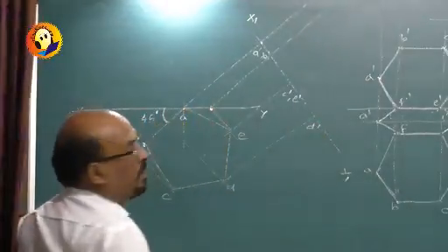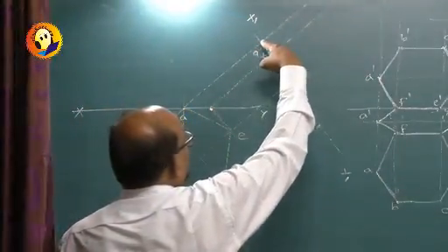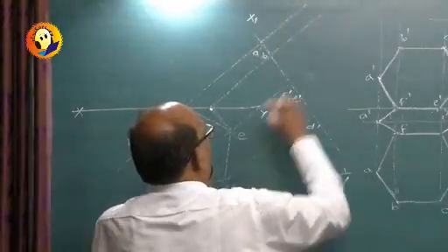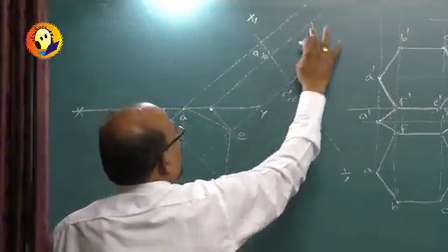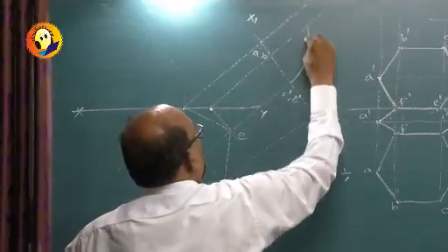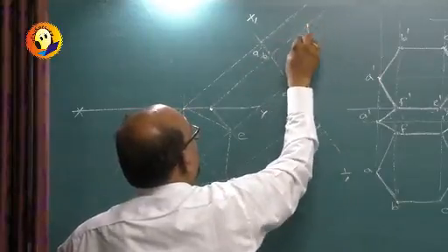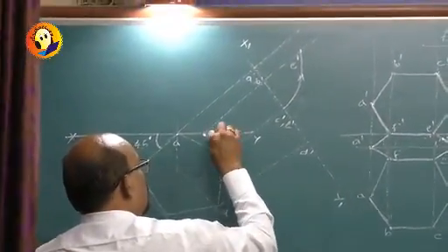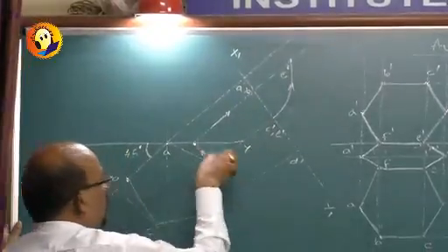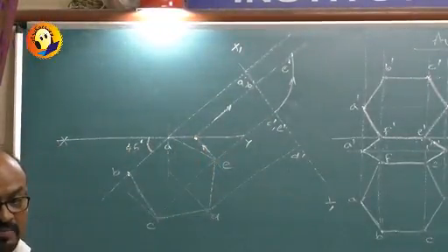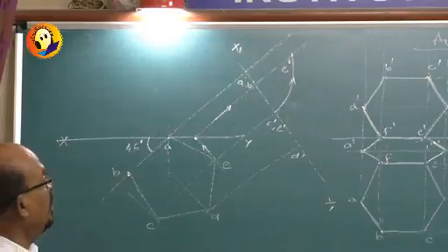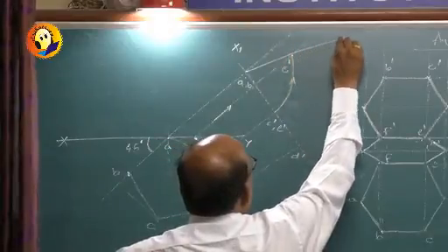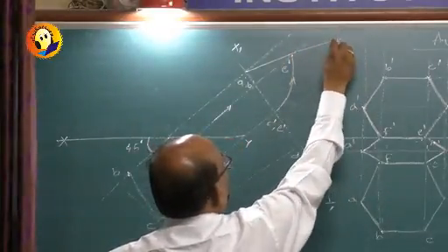So from there, we draw perpendicular, and from A dash, B dash till this C dash, E dash we rotate, because if we rotate it like this, this is where E dash should go. So I am going from here to this and from here till here, because E should be in VP. A is already in VP, so AE will be automatically in VP. Once I get this, I join A dash E dash and extend, and this will be rotated further onto it.